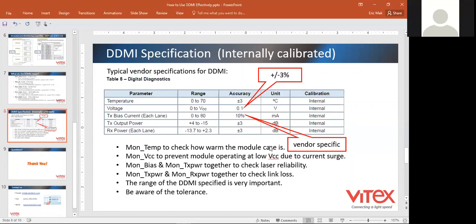At the calibration, when they build the transceiver. So when the laser starts to operate in the customer's place, this parameter cannot come from a power measurement, right? Because there is nobody to measure the power. So they just use the current, which was used to calibrate the power, to show it, right? So by itself it is an indirect measurement, right?